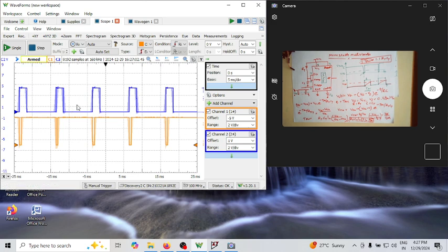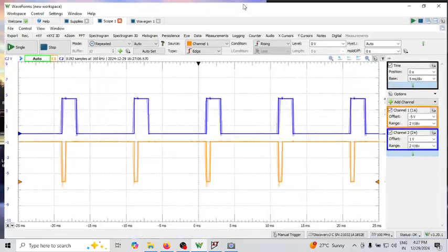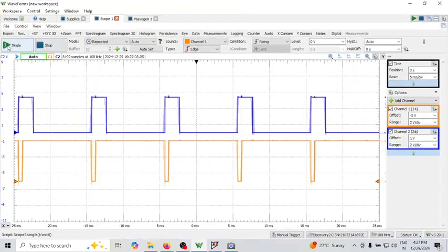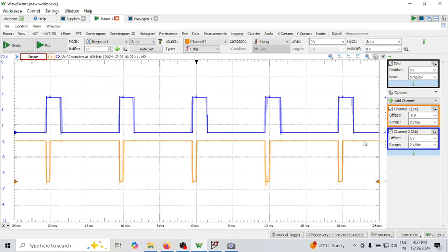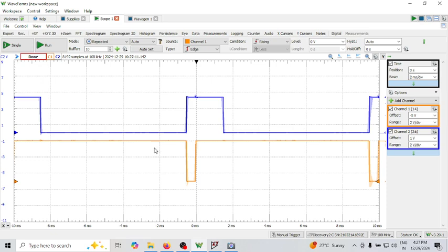See now, this is the type of waveform that I'm having. Let me stop it here. See, the moment I give a trigger signal, let me expand this more carefully. See here, this is my trigger signal. Let me make it 1 here. You can see when it is 5 volt, if you want to see channel 1, which is my trigger signal, this is 5 volt. When it is 5 volt, it is okay.